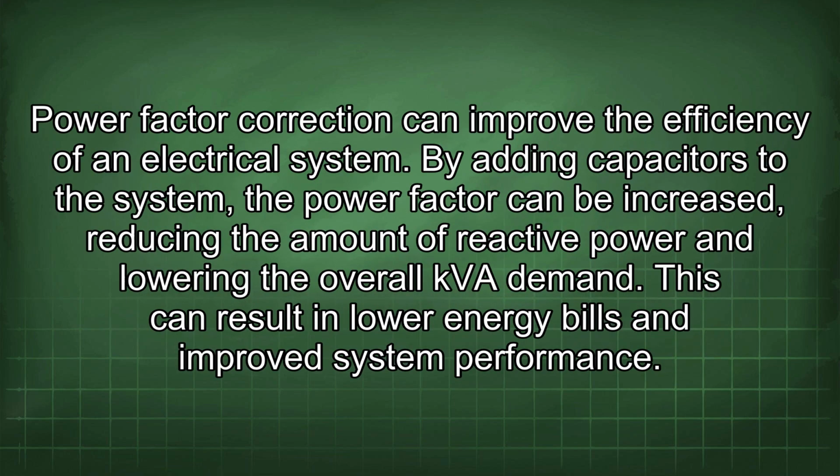Power factor correction can improve the efficiency of an electrical system. By adding capacitors to the system, the power factor can be increased, reducing the amount of reactive power and lowering the overall kVA demand. This can result in lower energy bills and improved system performance.